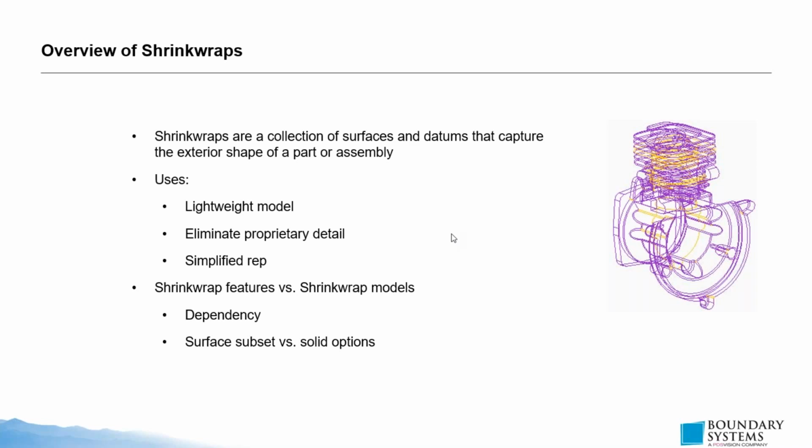One of the things people often do is make a STEP file, especially if you're working with another company that uses a different CAD software. It's true that will often remove a lot of this proprietary detail. However, if you're working with somebody else who also uses Creo, you definitely have a much greater risk of those files being damaged through these various encryption processes. A lot of times, certain surfaces or parts of your assembly will not load properly or encounter some errors.